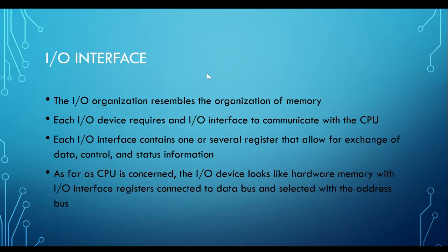Okay. Now, how do you access the I/O? Let's say I want to know whether this I/O, this LED connected to this I/O, is currently on or off. There are a couple of registers or memory associated with the I/O. Take out your MSP, you will find that it has probably 40 pins. The status of each of these I/O pins is connected to your memory.